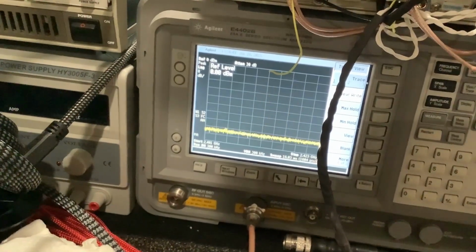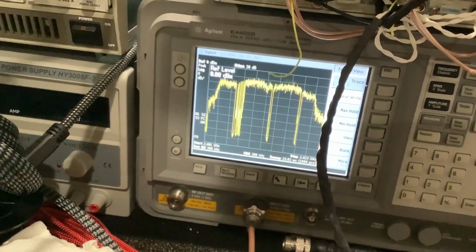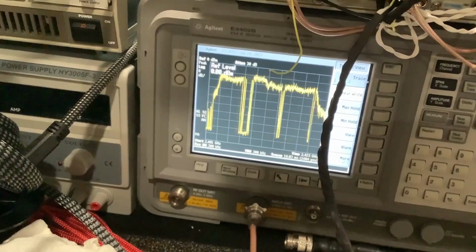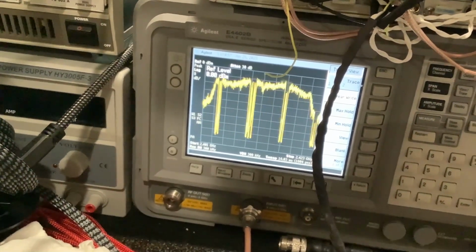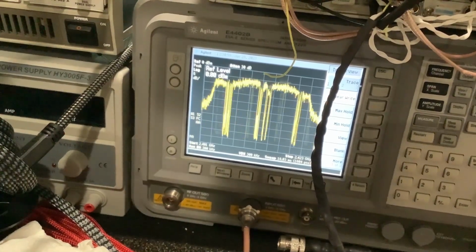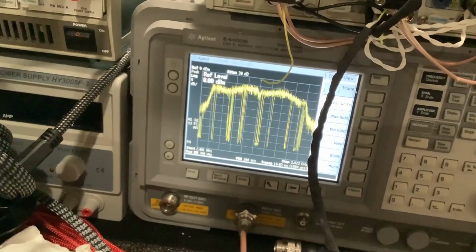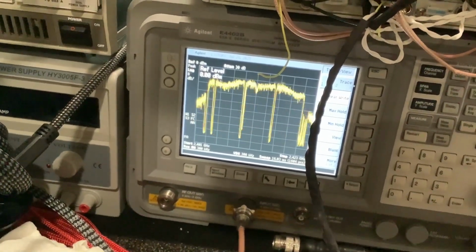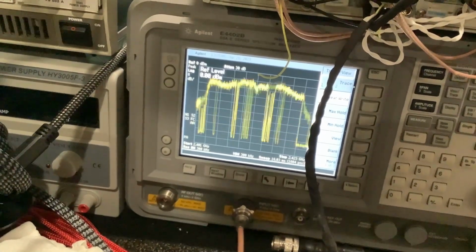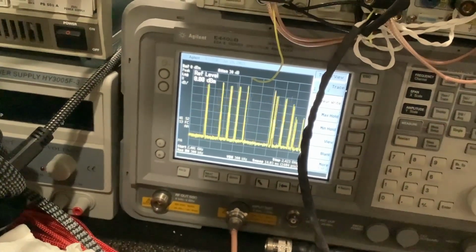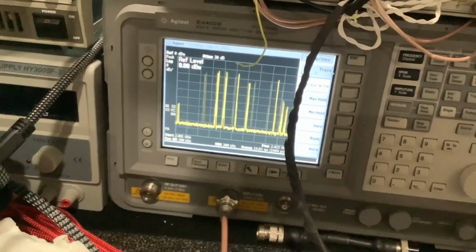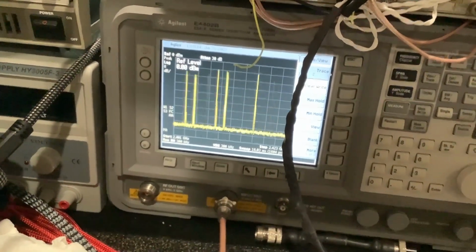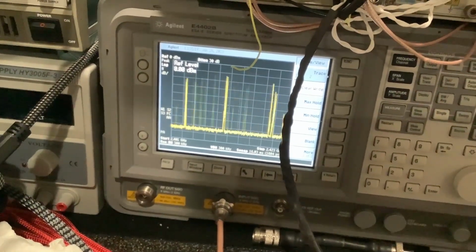If you've got stuff going on like what I'm doing there, which is simply browsing, and then I run a speed test, this is going to cause very different amounts of RF in very bursty manners to come out of this unit, or any Wi-Fi. This bursty manner of modulation could create noise and modulation on your audio frequency lines.